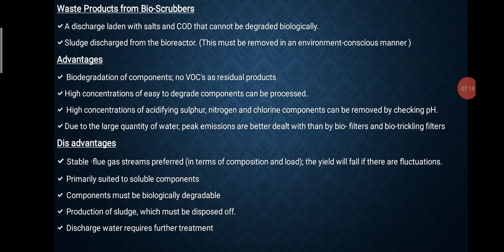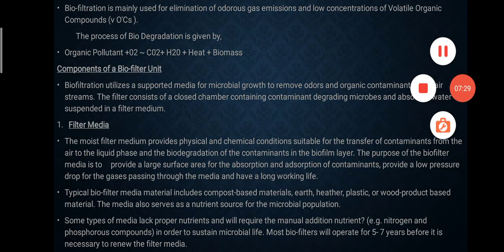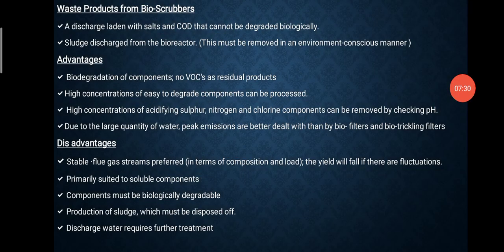Advantages: very good biodegradation of components, high concentration of easy to degrade components can be processed, high concentration of acidifying sulfur, nitrogen, and chlorine components can be removed with high pH.